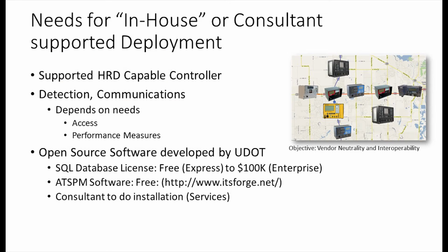In terms of the infrastructure that you need, if you're going to go with this open source option, you would need to have one of the high resolution capable controllers. And there's a list of those. I have pictures, so if you're very familiar with these, you'll recognize the yellow box or the blue box. But virtually all of the vendors that provide traffic signal controllers have a high resolution data capable controller. If you're using the 2070 variety, that might just imply a firmware update.